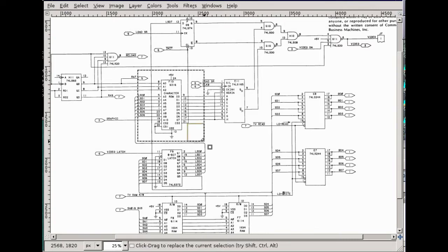We cannot see all characters in that random screen, but we see numbers, letters, lowercase, uppercase, also graphic characters, so it's okay. And the row scanning addresses, which are A0, A1, A2, are also working, so all the circuitry that is producing the character scanning is working.